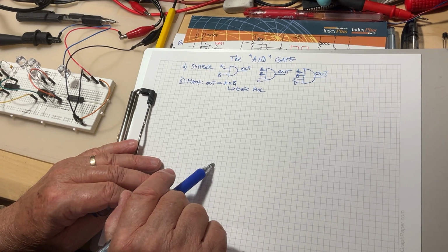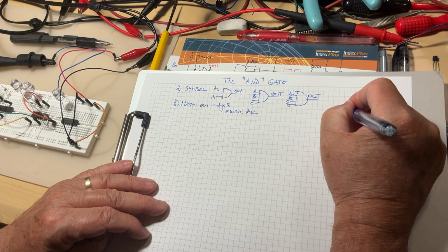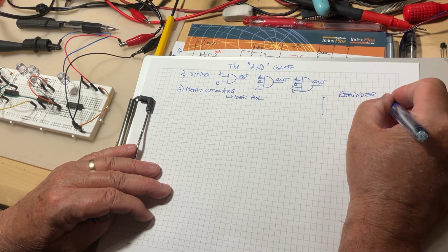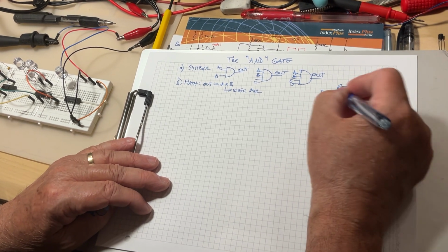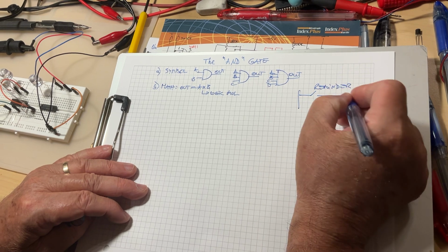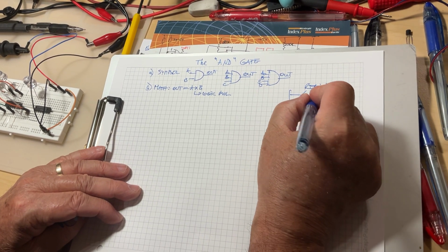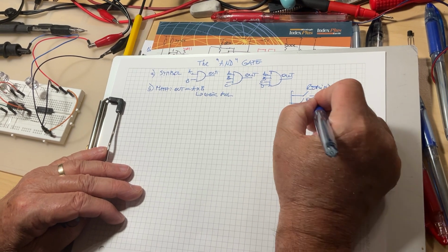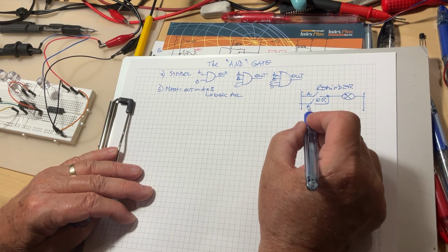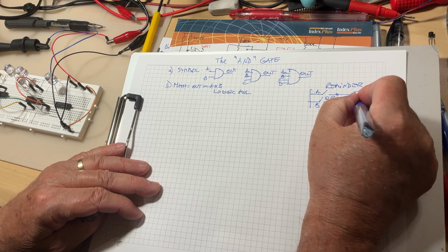Before seeing how this one is working, I'm going to remind you here, reminder. It won't take long. Using, like the last time, the relay ladder diagram. Remember the two contacts in parallel for the OR, A and B, the contacts. For the OR gate, either of these are on, the output is energized. So this is the output.